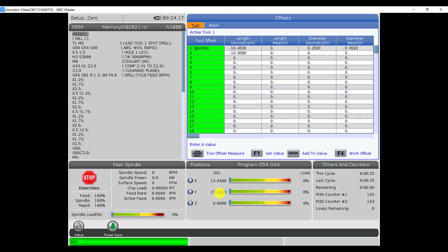Right? Because this is not dependent. This could be on a number of HAAS CNCs of different sizes. Okay, but you have to have values in there, especially when you're on a simulator. If you're at the machine, before you graph it, you should be ready to roll. Everything should be edge found or probed or whatever, and the tools should all be taught.